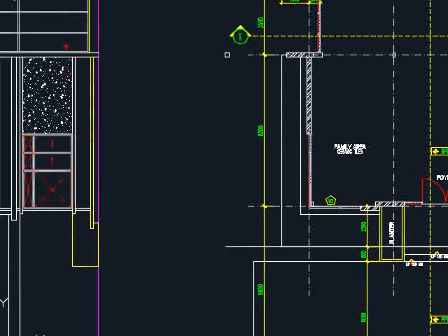Now the problem is, how do you keep this attached to the wall? Most likely there will be an extension from the ground floor beam that made a short wall here, so that this thing can be attached to that short wall. And then it will be dependent on the cantilever length here to decide whether you want to have the entire pieces here to be RC, or you consider that as a part of the brick wall.